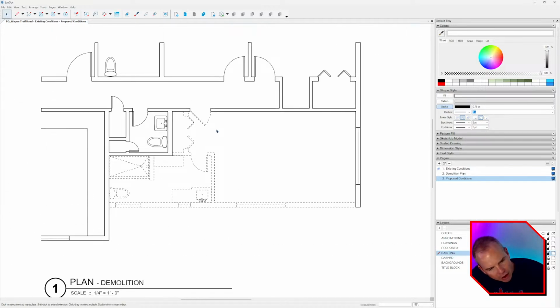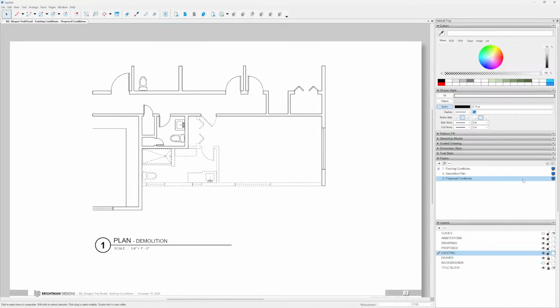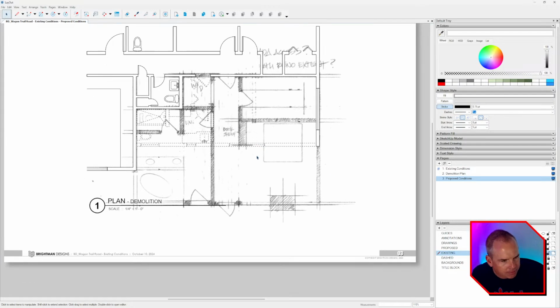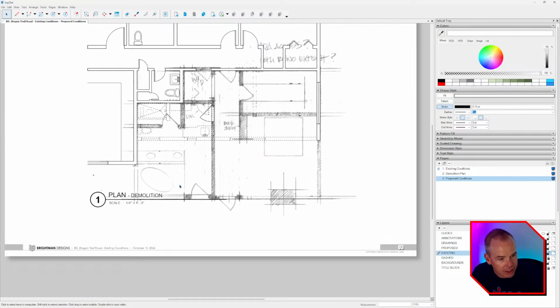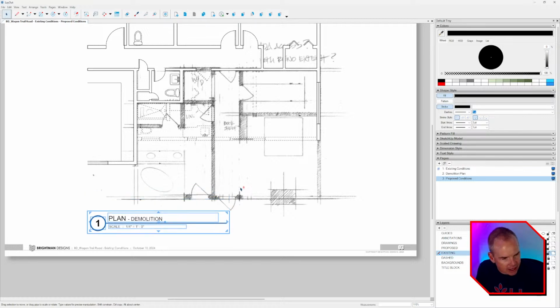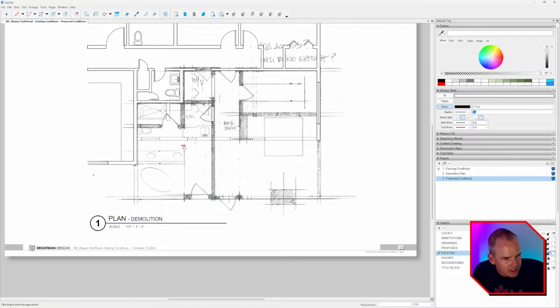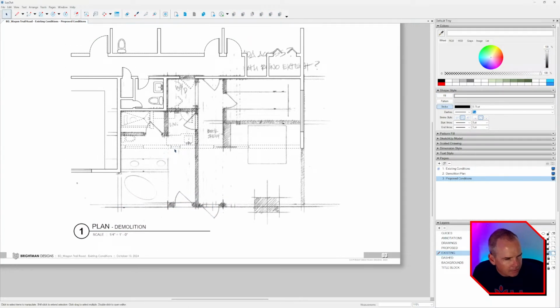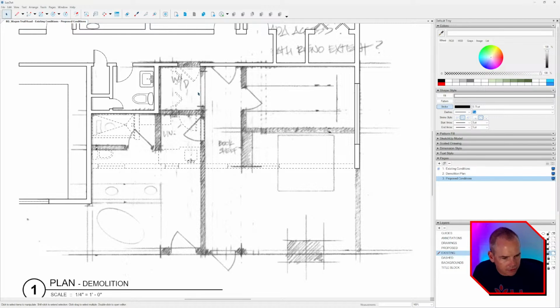And this way now when I add my new walls, by tracing our background here, we can then fill them in black. So new walls are hatched in black, and existing walls will just be 2 lines or hatched white, I guess. I'll nudge this out of the way, and all right, so let's start chipping away here.